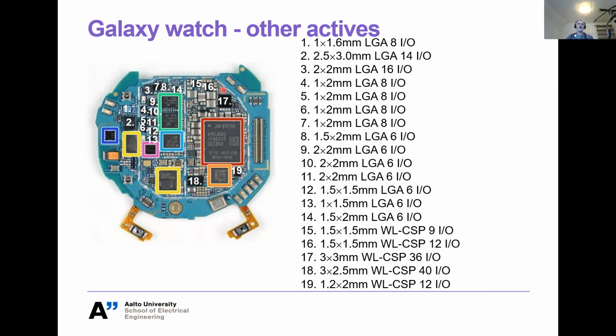So currently in these kinds of modern handheld consumer electronic products, the smallest chip resistors and capacitors are of the so-called 01005 size, which means that the length and width of the component is 250 micrometers times 125 micrometers.